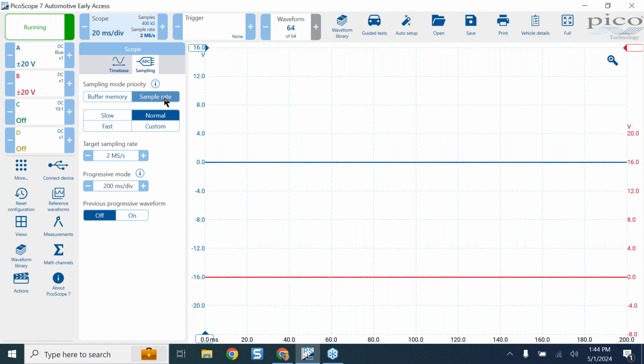Once you set it, I can't say you can forget it, because that's not the case. If we could, we would, of course. But once you get your sample interval where you want it for the speed of the signal that you're dealing with, it will stay where it's at regardless of the time base. And I think that's really important, especially for our power users. So what we did on the back end is we tried to make it fairly simple. We just used some pretty simple words. If you're looking at a slow signal, you can click on slow.